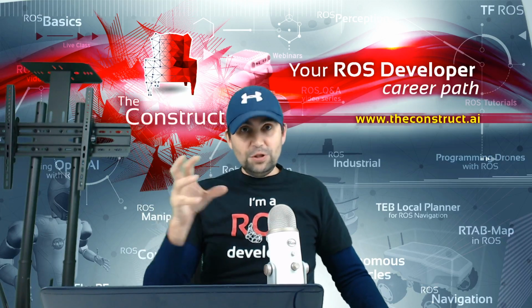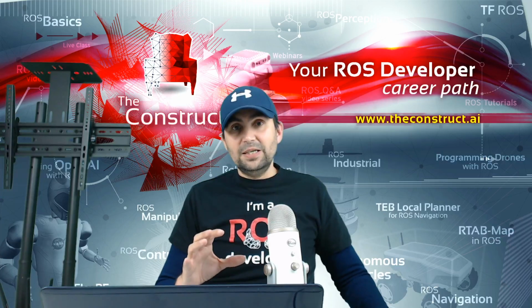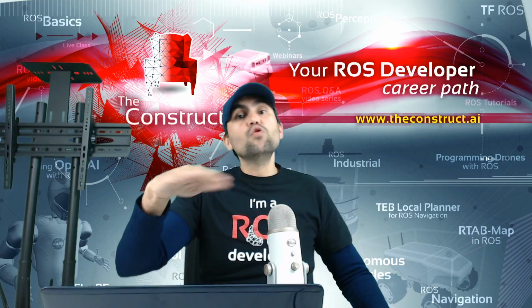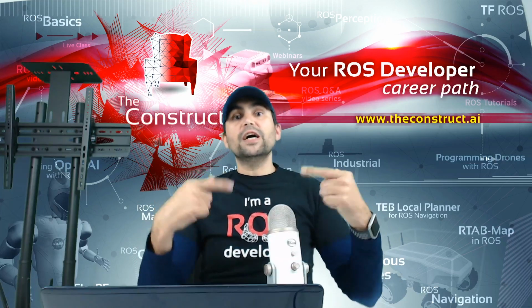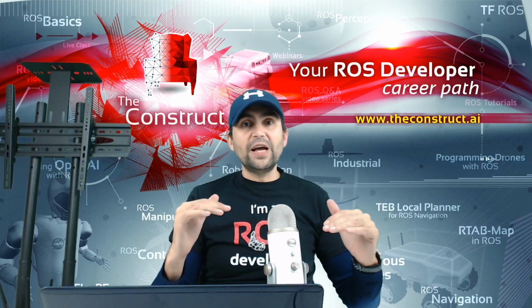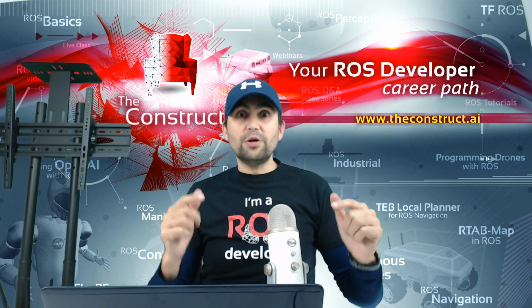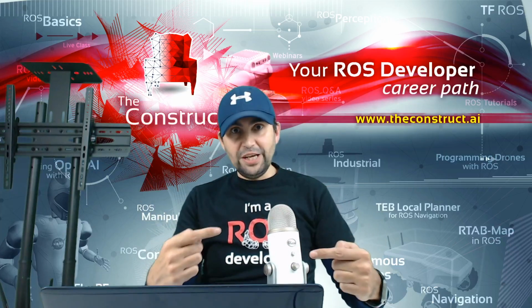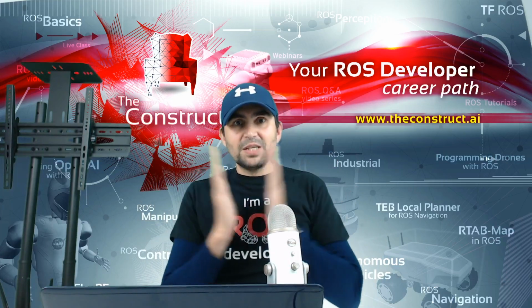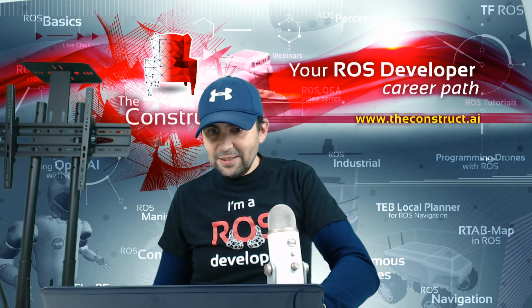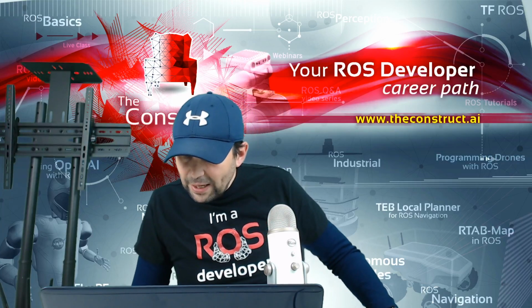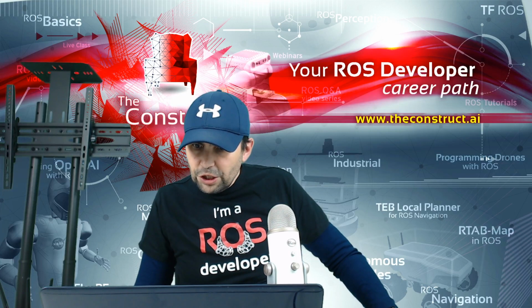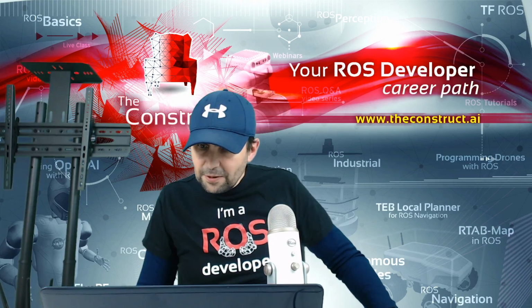Finally, we are going to use this map to localize in the area and make the robot move around using it. Most of the code is already provided. You and I are only going to work on creating the launch files for launching Cartographer for a specific robot, and the configuration files. That's what we are going to create together. Are you ready? Let me know on the chat. Danny Sobal says, Guillermo Rufino, so you need to add the 2 lasers to Cartographer and that's it? It's more straightforward than on Carto. Yes. Okay.